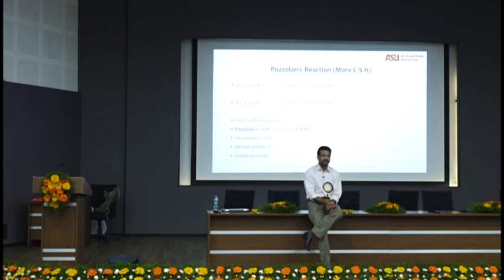How much is my alkalis in fly ash? How much is the free carbon in fly ash? What's the particle size of fly ash? If you answer those questions, then you can design a concrete mixture and do trial testing in the lab to satisfy all the performance requirements.